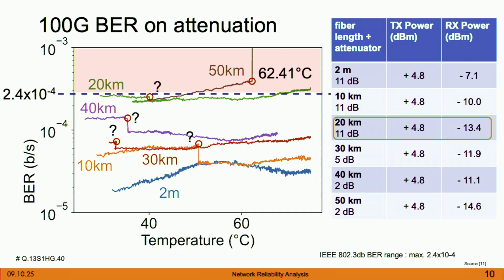Now, if you check bit error rates, usually they are way lower. This is the limit. It does not mean that you have a good bit error rate. You have a high bit error rate, but you don't have a good bandwidth. So that's the thing. With this transceiver, you can use 50 kilometers with high attenuation, but as you can see, it's already in the red section.